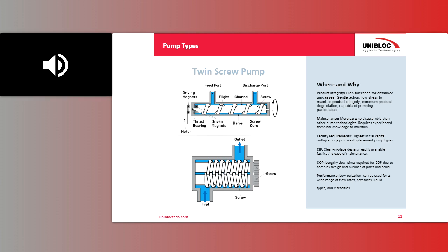The other big benefit of this technology is that a lot of times it's referred to as two pumps in one. It is a pump that can pump a thin, clean liquid like CIP solutions, but you can also pump the product, which is typically more viscous, through there, because of its speed range. These pumps are PD pump technologies, but they can run at what we call centrifugal pump speeds. They can run up to 3,600 and 4,000 RPM, depending on the brand. That gives you a wide range of scalability.